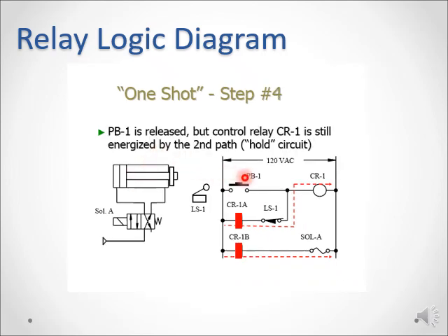Now, interestingly, you don't have to hold and press this PB1 because this parallel line is carrying the current as well. This is called the latch. Because of this latch, it will also carry the current and it will hold the switch, so you don't have to hold this switch anymore. So this will cause this control relay to be energized and hence this piston will still move forward.